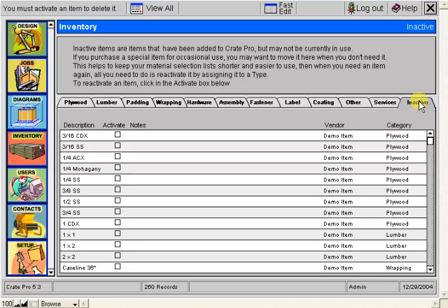Here, the 5-ply material would still be there, but the cost would be $0 and the time to cut and install the ply would be 0 as well. So, you may think everything is okay when you look at the cutting instructions, but if you take a closer look, you'd realize that you could be taking a big loss on the crate. Although CratePro allows you to delete an inventory material by identifying a replacement for it, oftentimes this isn't a great idea either. This feature is best used only if you're replacing materials of the same dimension.